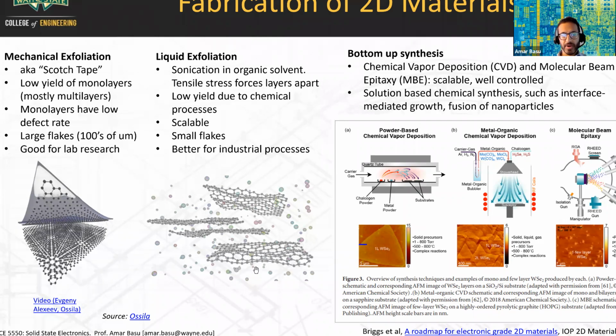So those vibrations create tensile stresses, tensile forces, and that forces these layers apart. So imagine if you start off with a material that has multiple layers of carbon sheets like this. Now the carbon sheets are kind of stuck together with something called van der Waals forces. So if you shake it enough, those layers can come apart.